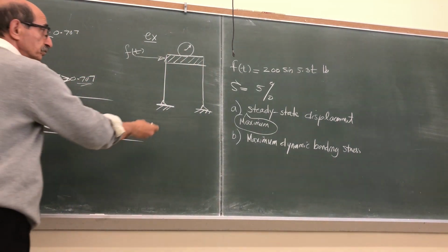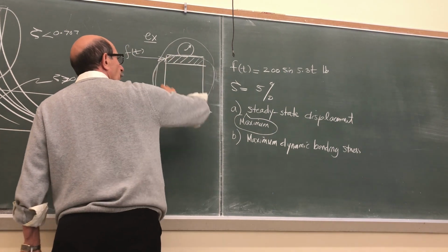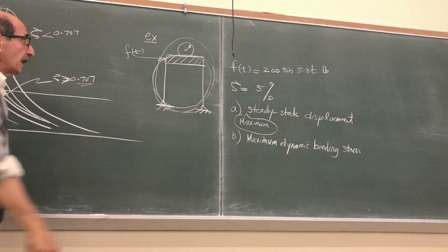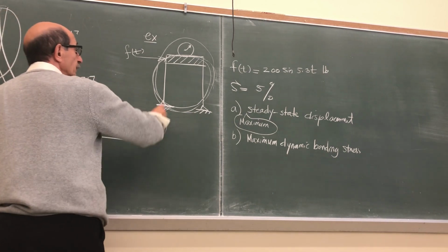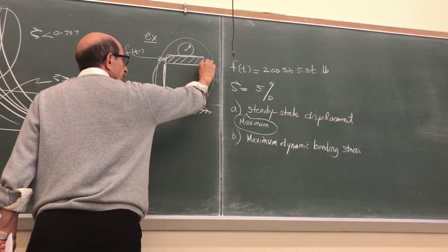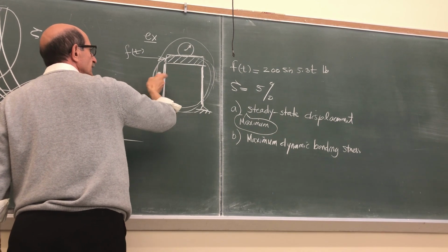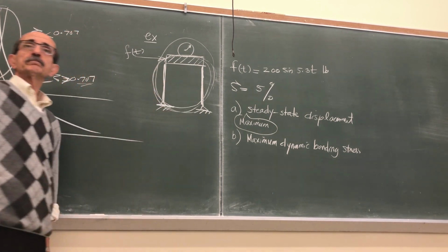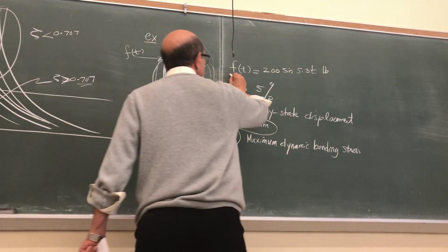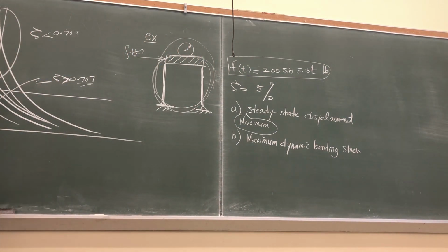In other words, we want to build a foundation or some support mechanism to hold this rotating machinery, and knowing that this is made of some materials, the details of which I'll give you, how much would be the maximum stress that develops in these beams. So we can find out if you put this machine on top of this, will it be safe?